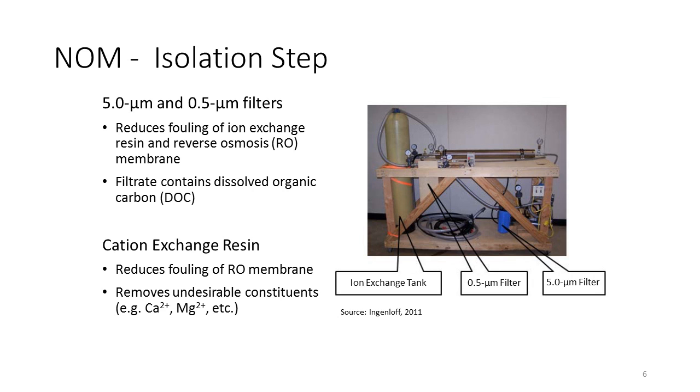And then from there, your filtrate goes through your cation exchange resin. And what we're trying to do is remove your metals such as calcium, magnesium, and other metals that may be in your solution in order to reduce the fouling of your membrane, as well as removing those compounds that could competitively adsorb to or complex with the natural matrix in your experiments later on.